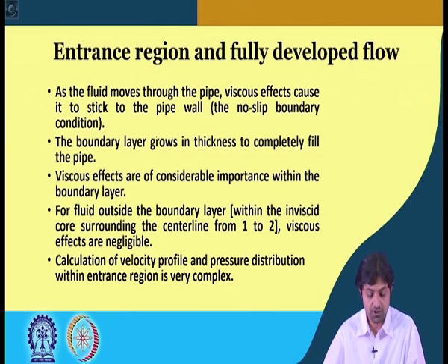The calculation of velocity profile and pressure distribution within the entrance region is very complex and therefore outside the scope of this course. So we are not going to calculate the velocity and pressure distribution within the entrance region. The only thing that you should remember is the entrance length, depending on the Reynolds number.